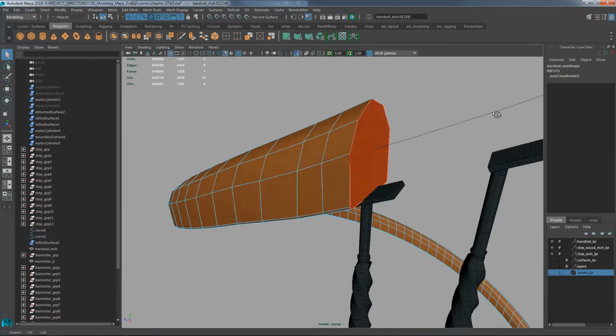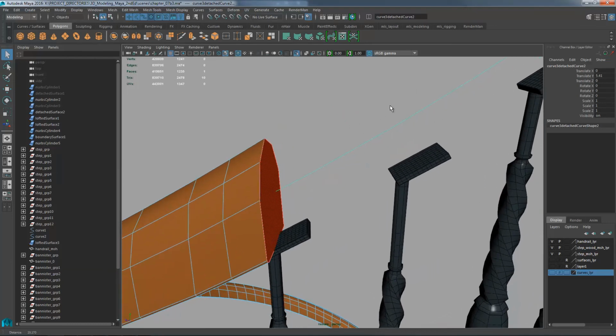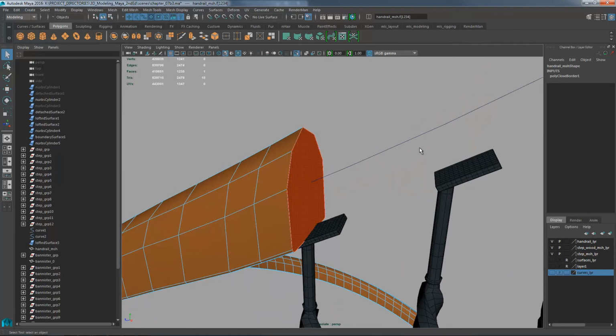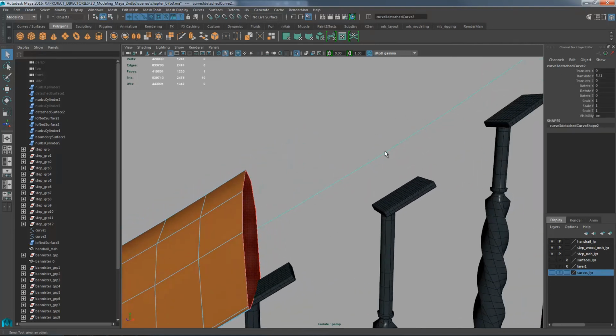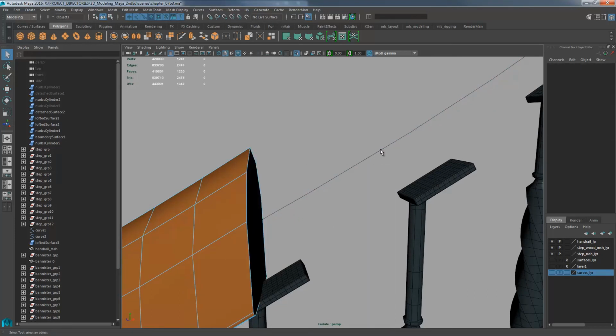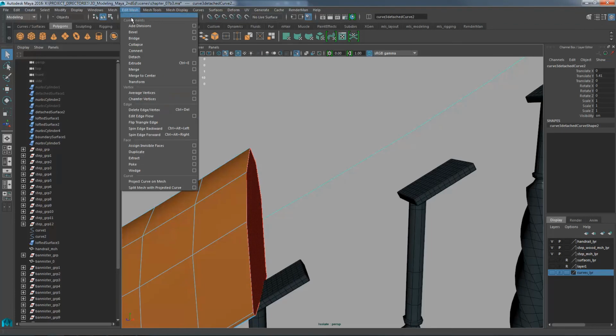Then select that polygon. Select the curve. The curve should be highlighted in green. So okay, let me say that again. Select the polygon, Shift select the curve. The curve should be in green. If it's blue, you did it wrong. Just try again. Make sure that the curve is in object mode before beginning this. So polygon, Shift select, and then run a normal extrusion.